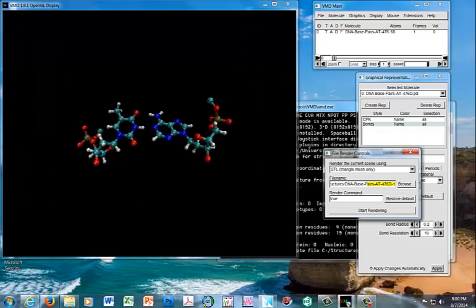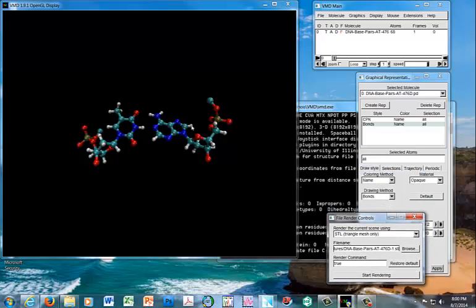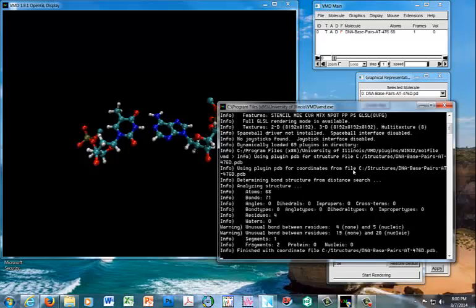Then you've got to make sure that at the end of this it says STL. The next thing we've got to do is actually a little counterintuitive. We've got to scale this to a certain extent so we can go ahead and import that into the next software program that we're going to use, which is Tinkercad. So to do that, you have to use the command line, and we're going to type in code that says scale to 6.0.